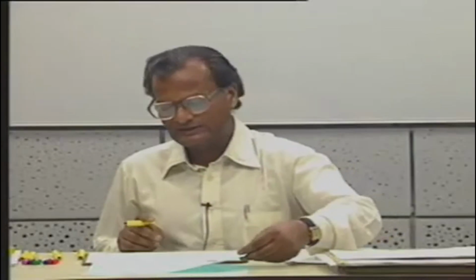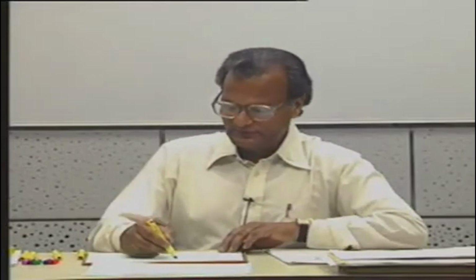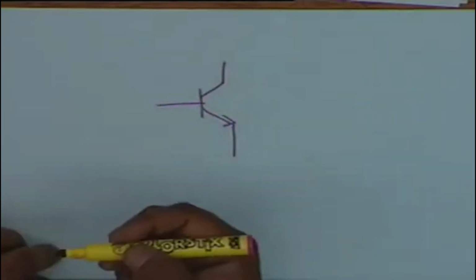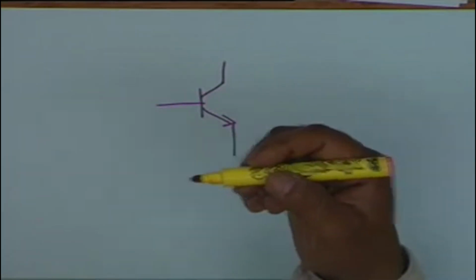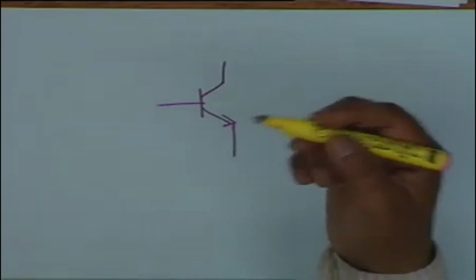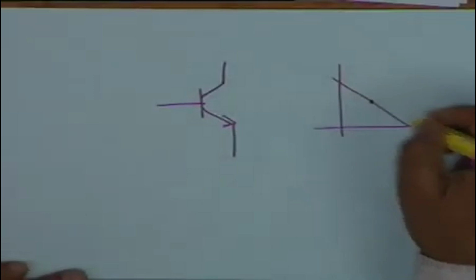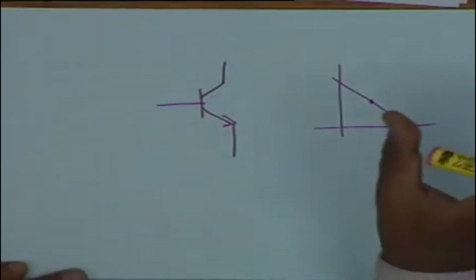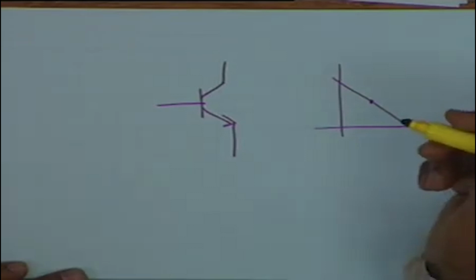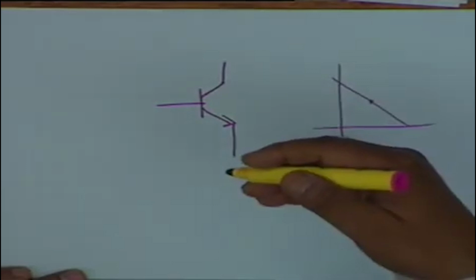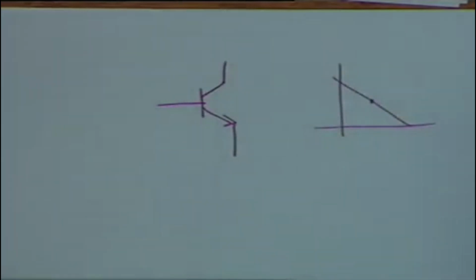Now let us look at a transistor, and for being specific, let us consider a common emitter transistor. We have to use a DC power supply VCC, and resistances to bias the transistor properly. We have to determine a Q point at the middle of the load line to make the maximum possible swing. For maximum linearity also, the characteristics are maximally linear near the middle; at the saturation point or at the end they become curved.